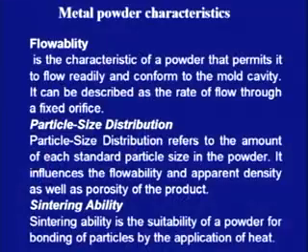If it is not flowable, it will not reach all the corners of the die cavity, and the final product that we get will be a defective product. So, flowability is an important characteristic of metal powders, and metal powders should have adequate flowability. It can be described as the rate of flow through a fixed orifice.